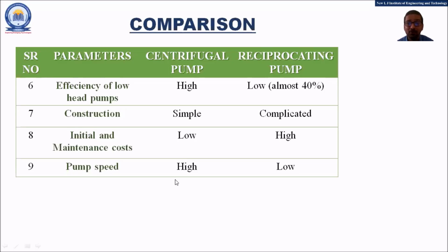I hope you have understood my simple answer to the technical question which I asked you. To be more simple, the pump speed in case of the centrifugal pump is very high in order to increase the centrifugal force. And by increasing the centrifugal force, more kinetic energy of the liquid will be converted into more pressure energy of the liquid.